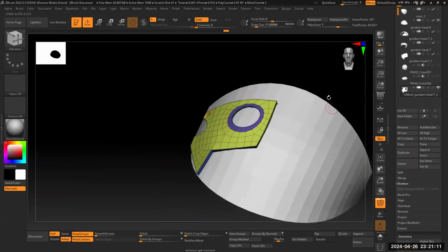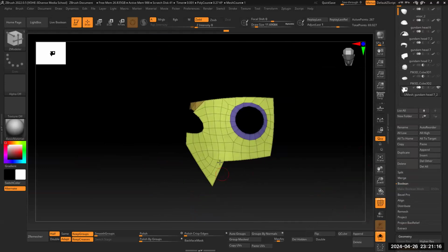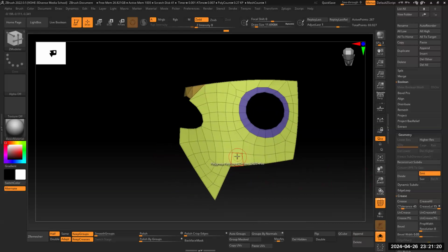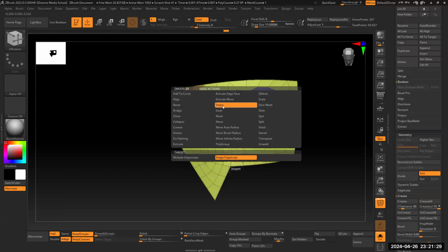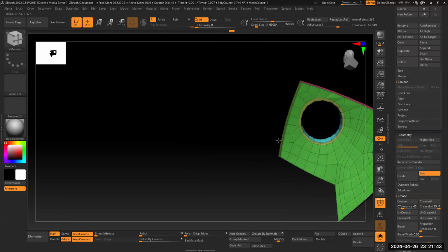Oh, knife curve, I don't use it so much, right? If I want to cut something, because knife curve will end up in triangles or weird cuts at places you don't want, right? I prefer to use insert single edge loop to cut stuff, right? If your thing is all looped properly, then it should cut properly, so you can sort of check your topology also. If it loops round and round and round like that, something is wrong, probably on the behind part, right?